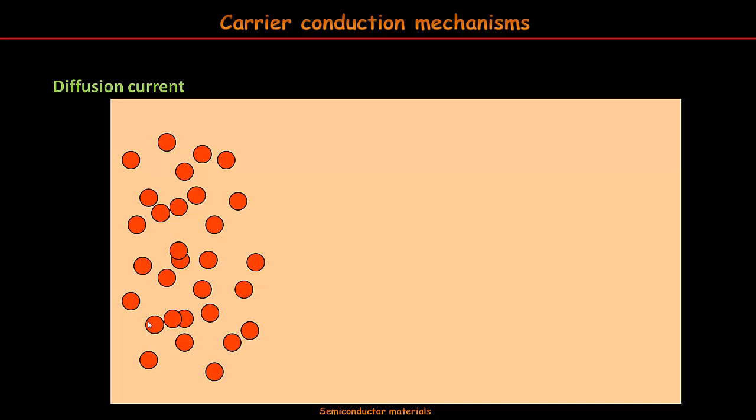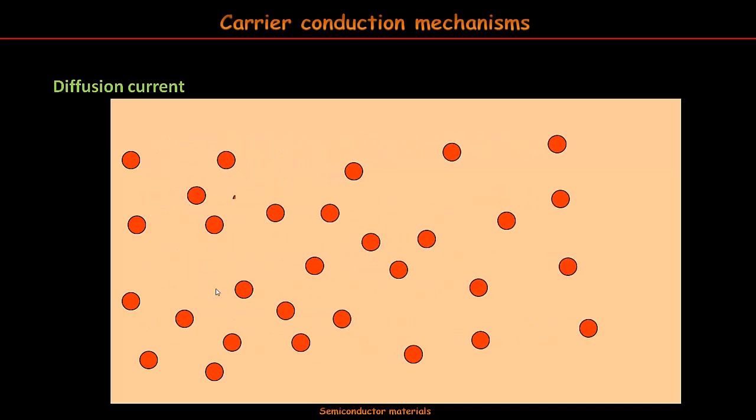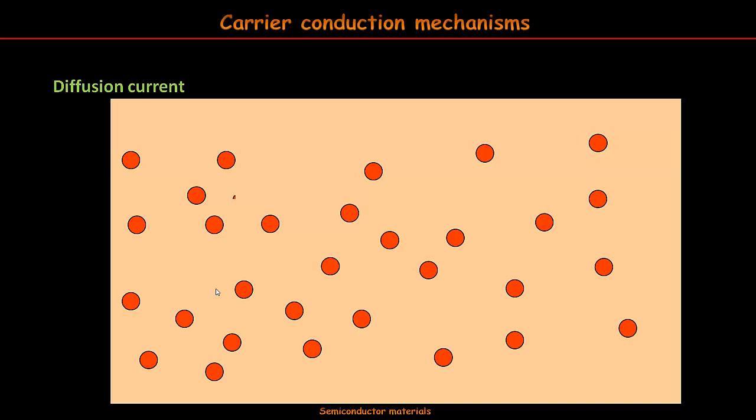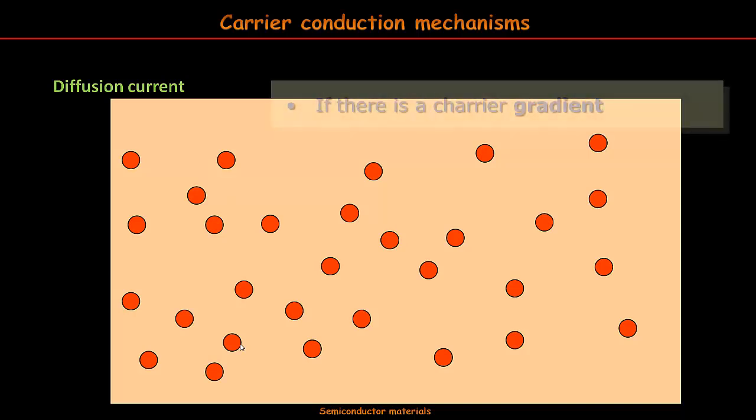These free charge carriers all share the same charge, positive or negative, but the same. Then, by simple electrical repulsion, they tend to move away from each other, filling the area on the right side of the drawn bulk material. We are seeing a diffusion current, and we have discovered that this is caused by a gradient in the concentration of carriers.